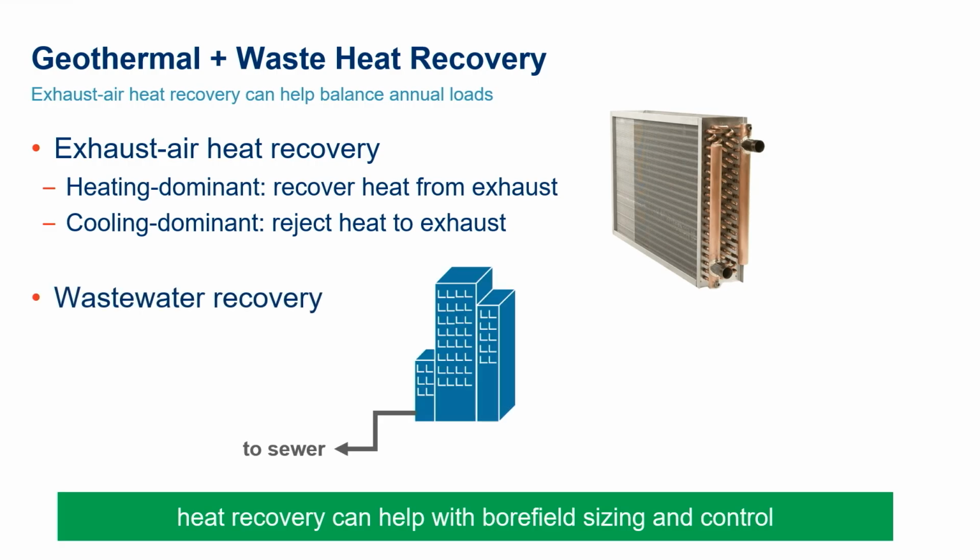Wastewater is another energy recovery opportunity. Buildings that drain high amounts of heated water are ripe with opportunity to recover heat that could be directed to the Borefield and to the building being served by the system. Again, this could help reduce the size of the Borefield and/or help maintain an ideal Borefield temperature.